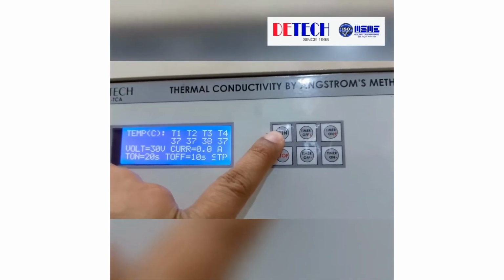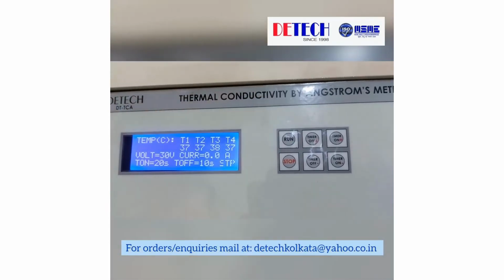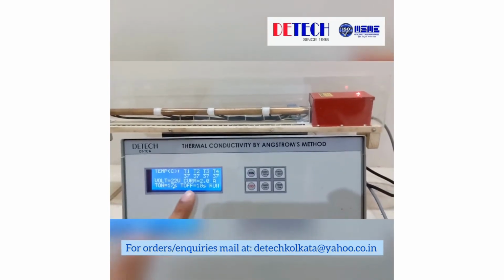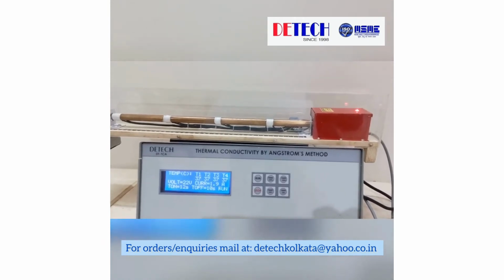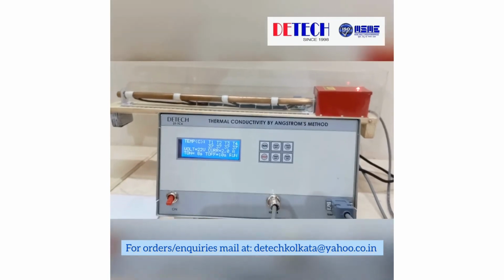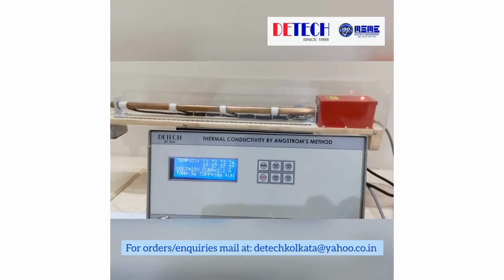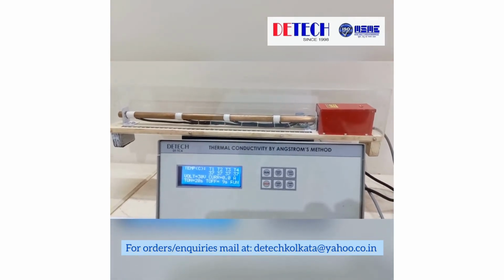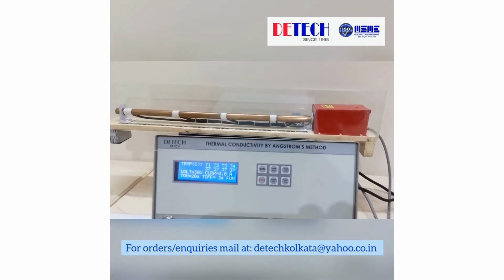And we will now press the run button. As soon as I press the run button, the heater is on. Here the current is around 2 ampere and the voltage is around 22 volt. So the heater is switched off. It will be off for 10 seconds and again it will be switched on for 20 seconds.